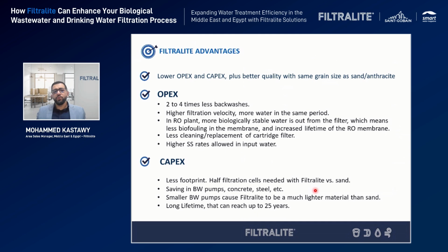So let's say that you are doing one backwash every day. Then you can have this one backwash every couple of days, up to 4 days. Of course, again, it depends on the full process and on the water quality. At the same time, the availability of these voids or this porosity gives you a higher filtration velocity. Like we said, we can reach up to 20 meters per hour because you are giving more space to the water to go inside.